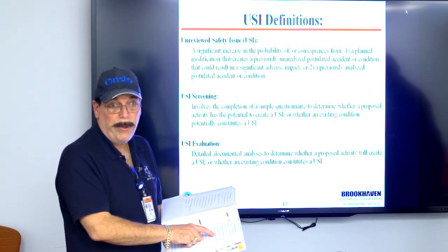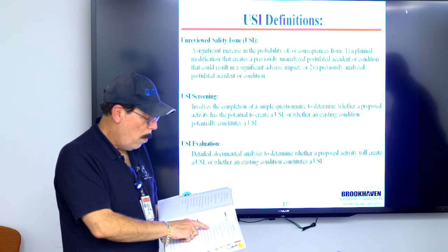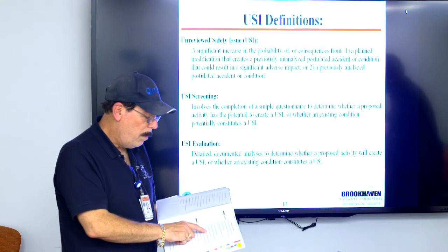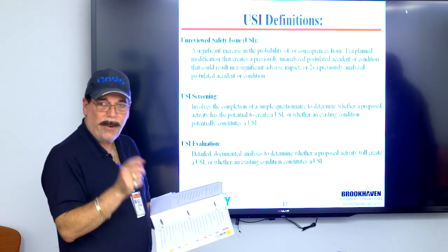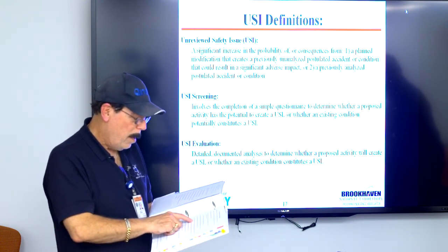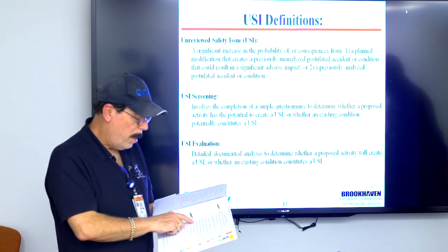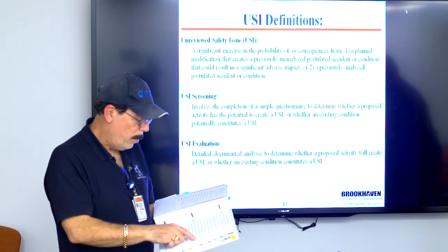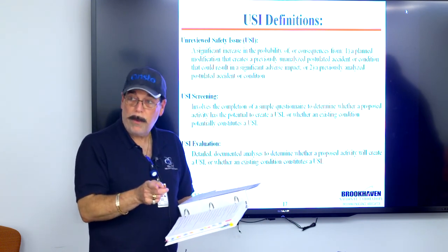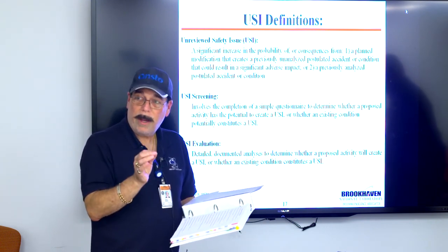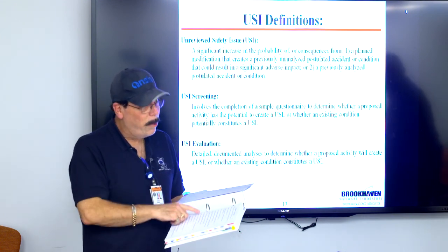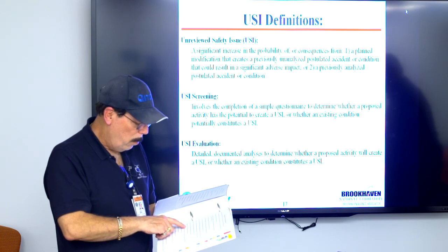Work planning and control procedure invokes the USI. Authorizing operations and performing maintenance invokes the USI. Procedure for safety system work permits. Anything that has credited control, when we work on it, gets a separate safety system work permit. Radiation safety component configuration management, radiation air monitors configuration management, PPS configuration management, procedure for software change control. We don't think about this, but things that affect programmable logic controllers and the way the machine operates, that is something we have to be very careful of making changes to.